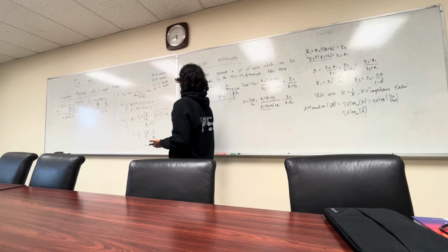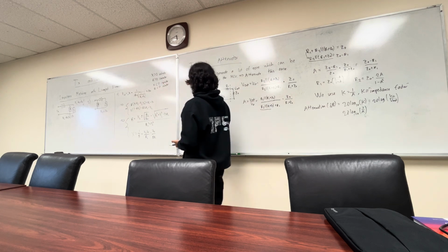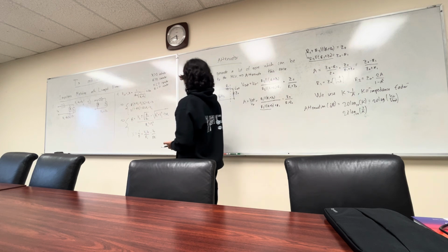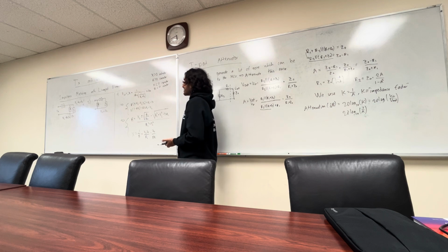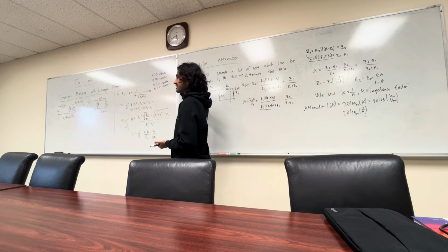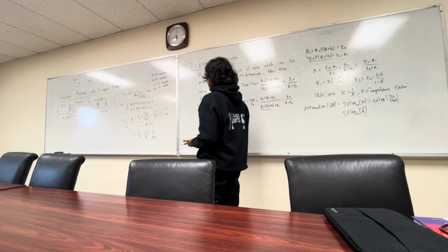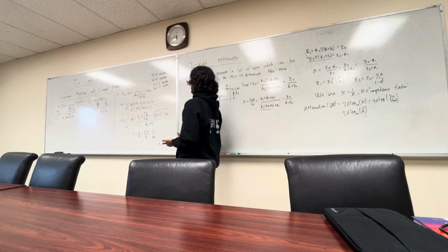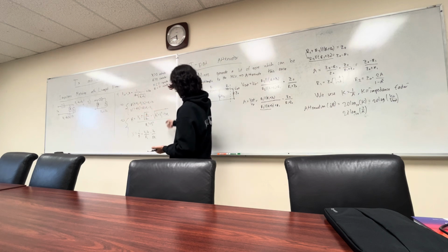So whether this is for IC stuff, where you won't ever really do impedance matching like this, or more from an RF microwave perspective, whenever you can get away with using a capacitor over an inductor, it's just better, because inductors have a bit more parasitics to deal with, more of a resistive loss. With capacitors, you don't really care. The quality factor you do care about, but not as much as for an inductor. So this is scenario 1, and we're going to see how scenario 2 compares to all of this.